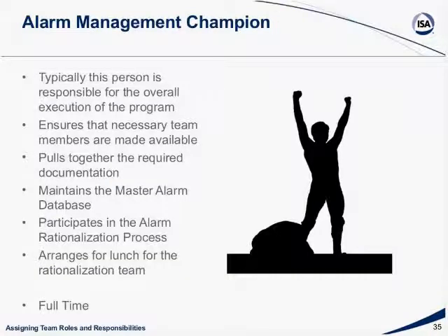Well, let's start with the alarm management champion, okay? This is the person that's responsible for the overall execution of the program, okay? This is the person that interfaces with the different departments at a facility to make sure that the team members are made available for the rationalization process, okay? This is also the person that pulls together all the required documentation that you need to perform the rationalization. They maintain the master alarm database.